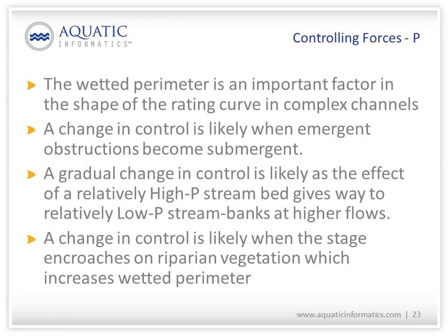Another one of the variables from the head loss equation that we need to pay very close attention to is wetted perimeter. This is related to things like channel shape and channel rugosity, but it's much more than that. It has to do with the surface area in effect over the length of the control reach. Things like ice dramatically change the wetted perimeter, the contact area of the water with an unmovable solid. So things like vegetation change the wetted perimeter quite dramatically.